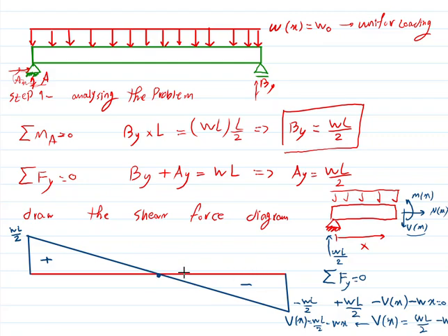And in here, it says I am equal to the amount of the support reaction. And then from here, if you pass the half of the beam, the shear force actually says, okay, the support reaction is gone, and now I get forces downward. So it cannot be in the same direction as the sign convention that we had. I need to be upward to actually cancel out the forces. And you see, because the shear force direction changes and it's upward, we get a negative amount.